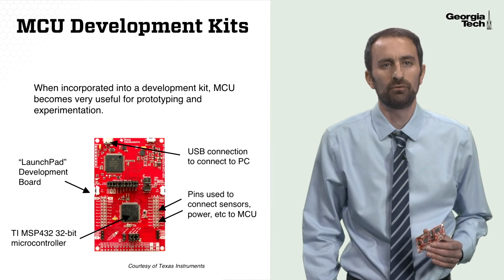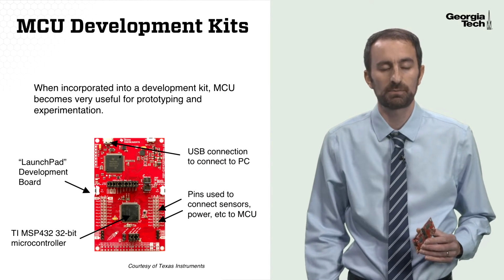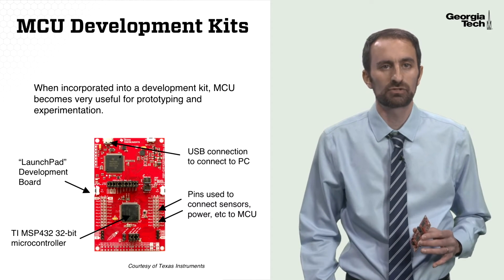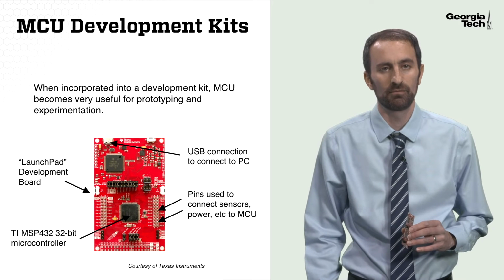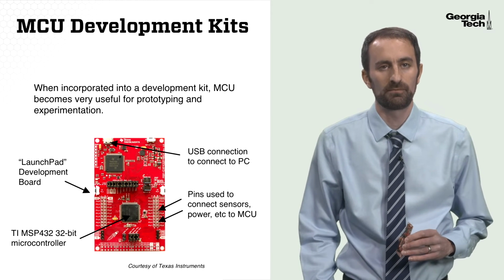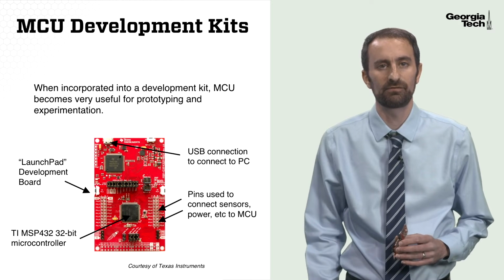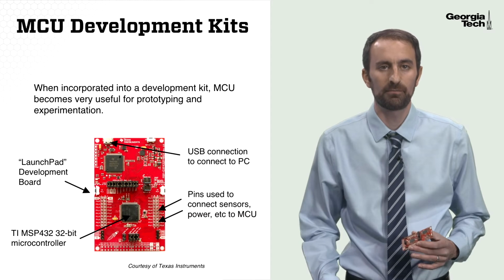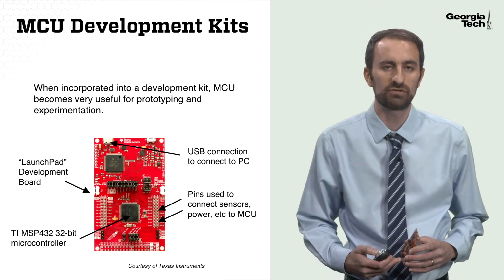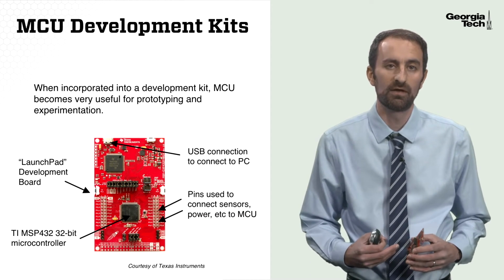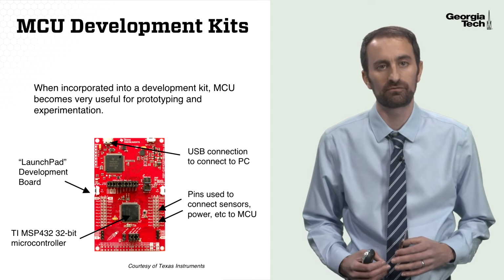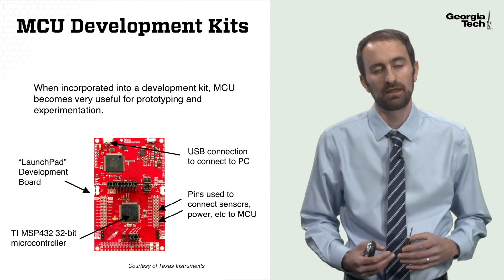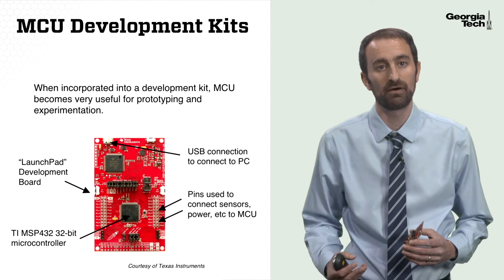Here's a close-up view of the MSP432 Launchpad development board from Texas Instruments. When this microcontroller is integrated into this development board, it becomes very useful for prototyping purposes. There are several key elements that are important. There's a USB connection to a PC, and there are header pins that allow you to connect GPIO pins, or input-output pins, from the microcontroller to external devices such as sensors and motors and servos, etc. They also allow you to power the microcontroller from a battery quite easily.